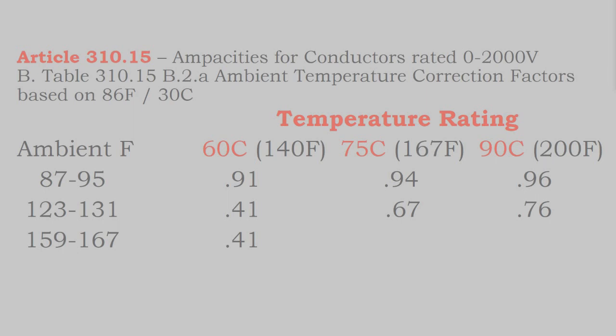When you increase the conductor size, the resistance of the conductor goes down. It's more efficient and it generates less heat.